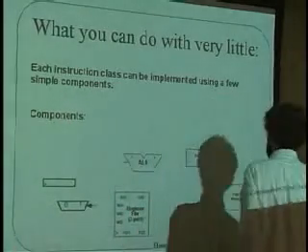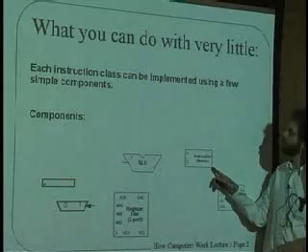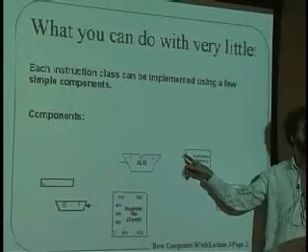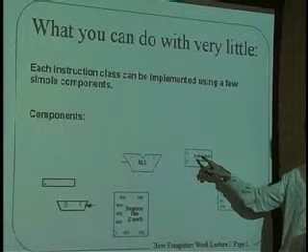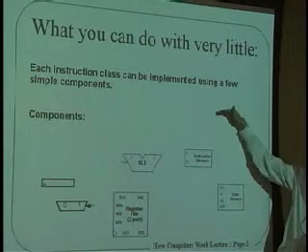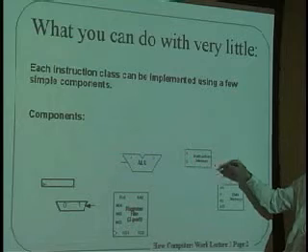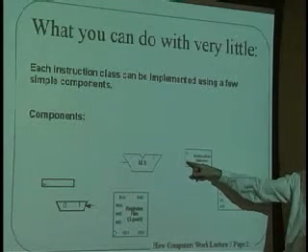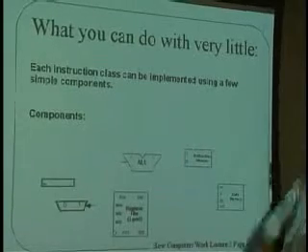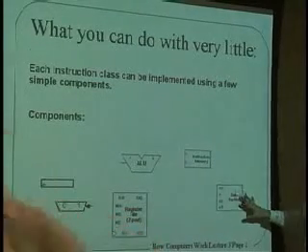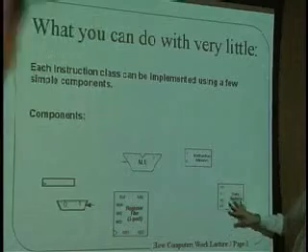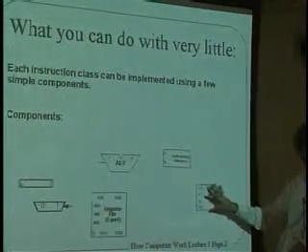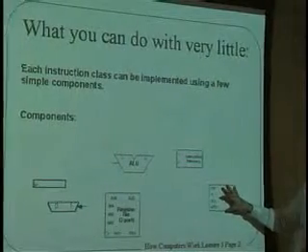Finally, amongst the blocks that we're going to use is going to be an instruction memory over here, and that will have an address input saying which address in the memory we want to have access to, and that again is how far from the beginning do we want to read a particular word. And it'll also have a data port which is going to be telling us what the data is at that particular address. We'll also have a data memory over here which we're going to be using for reading and writing different data items in the memory when we do loads and stores.